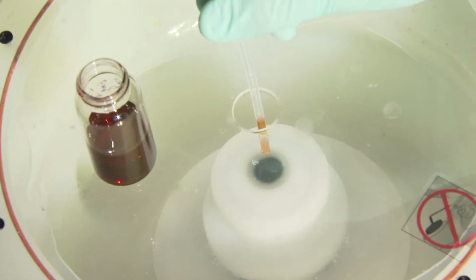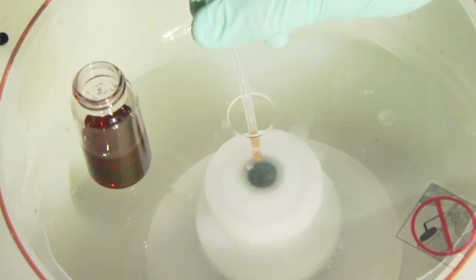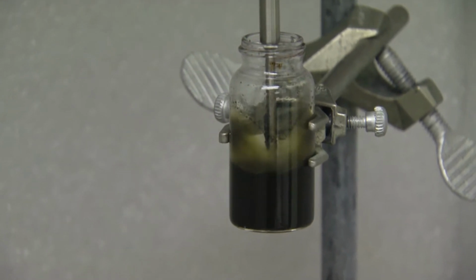To align the carbon nanotubes, one of the ways to do that, especially over a large area, is to use a liquid to flow the nanotubes across the substrate. This is kind of like flowing logs along the river. Then these logs will be aligned along the direction of the flow of the river. So this kind of phenomenon can actually be applied to align carbon nanotubes over a very large area without using sophisticated methods.